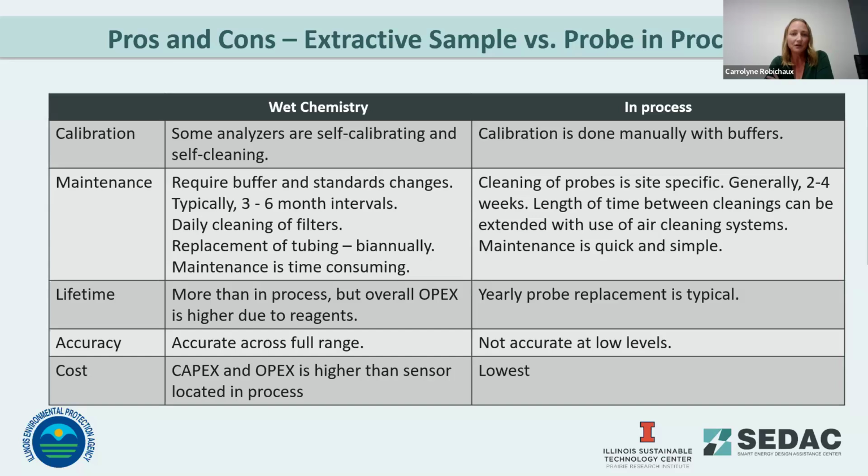The probes for ISE, the tip of that probe is glass. The measuring is done at the glass. So damage can happen. Typically, a probe will last about a year before replacement. You know when to replace by it not calibrating anymore. Or if you see a lot of this going on, that's swimming, right? So if you are no longer able to maintain an accurate measurement, then that probe needs to be replaced. Probes are considered consumable for ion selective electrodes.